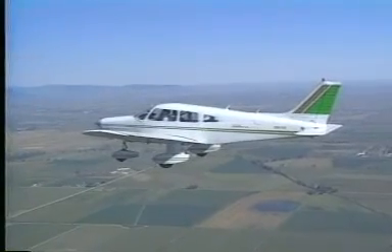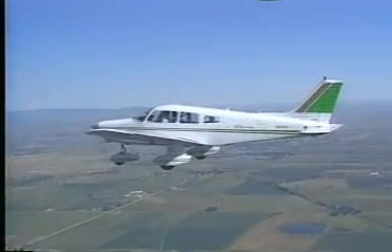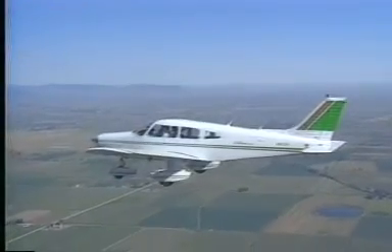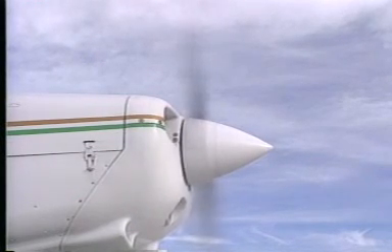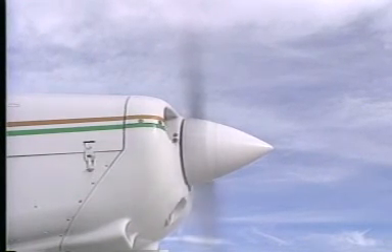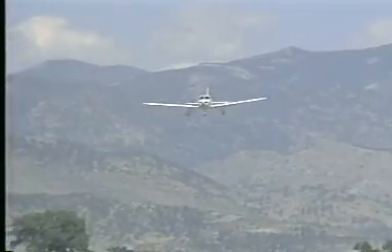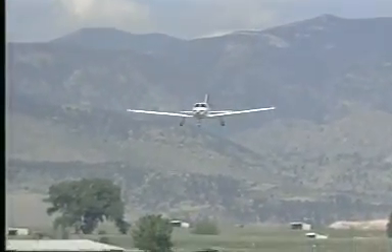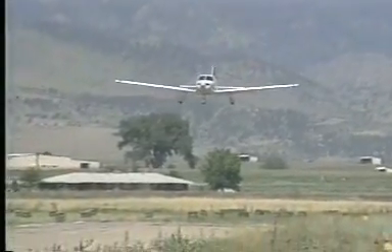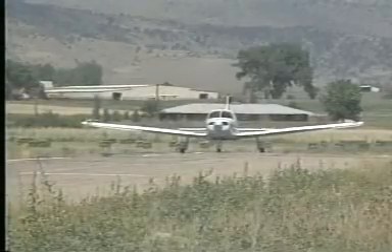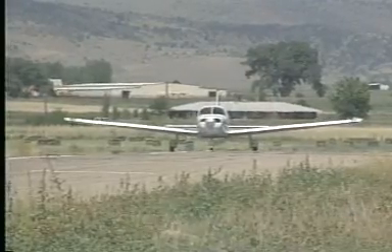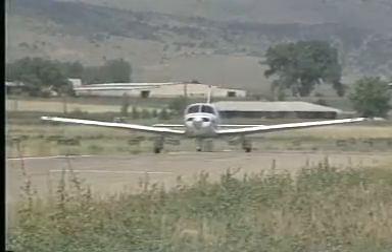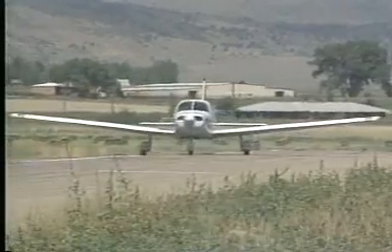Altitude is a primary item affecting performance. Specifically, as you gain altitude, the atmospheric pressure decreases. With a normally aspirated engine, the less dense air reduces engine power and overall airplane performance. It's essential that you consider this when operating at high-elevation airports. Air density also decreases as the temperature rises because air molecules expand as they are heated. Therefore, the performance of your airplane diminishes on hot days.